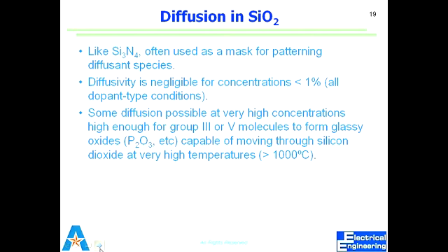So, as a process engineer, I have to know what mask I can use, because my desired doping profile and doping condition will tell me if I can use silicon dioxide or silicon nitride. In both cases, that will be different. Just like in etching, we saw the concept that the selectivity defined how thick the mask material needs to be.